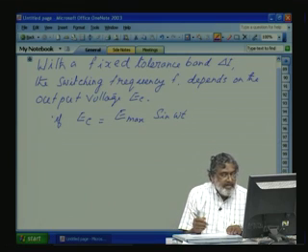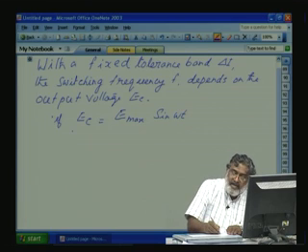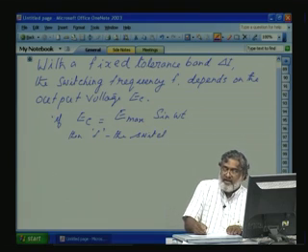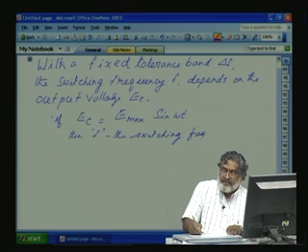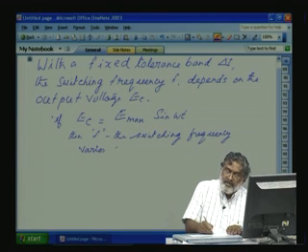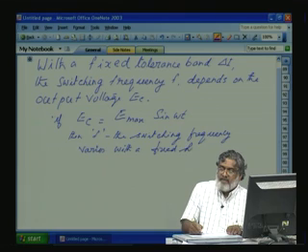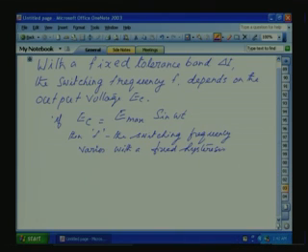That way we slowly introduce the hysteresis band required for motor drive application. Then what happens? The inverter switching frequency F varies for a fixed hysteresis band delta I. So, let us go back to the previous equation.